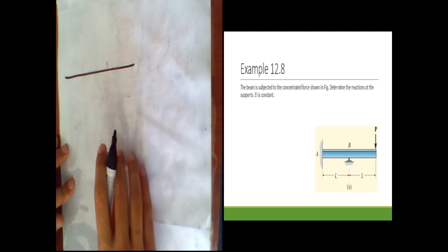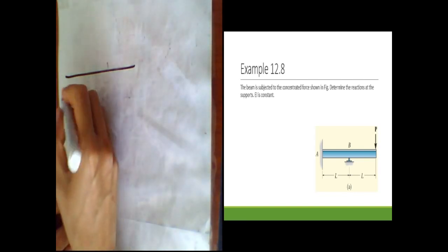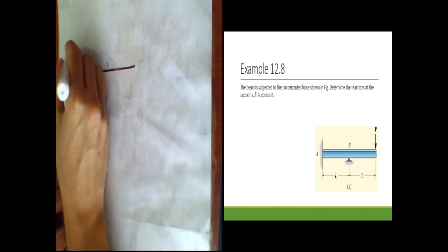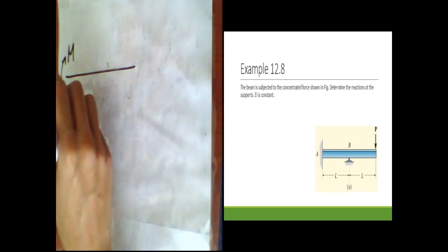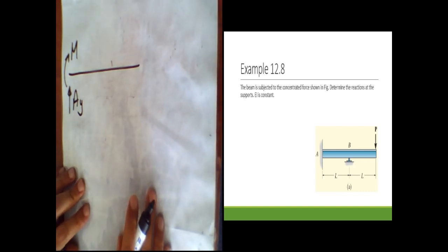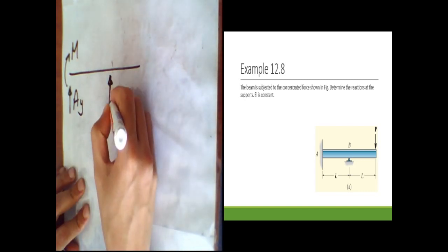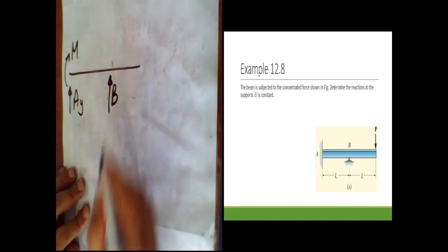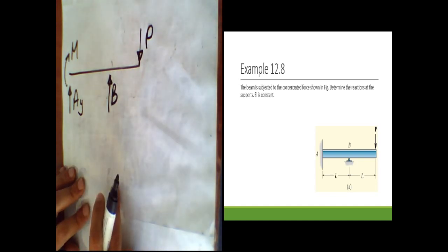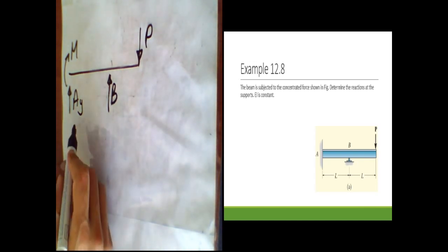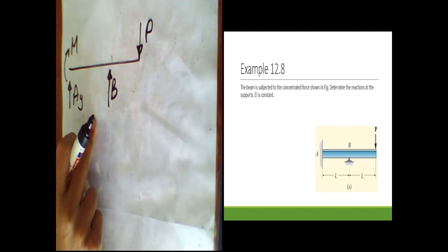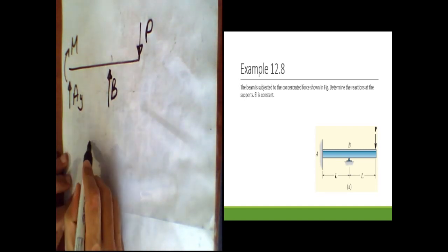Normally, if I want to draw the free body diagram, here I have Ay and a moment. Also, I eliminate the horizontal force because Ax is equal to 0, therefore I don't write it at A. This is By, at B. So we have 3 unknowns, but we can apply just 2 equations, therefore we cannot easily find them. This is the whole free body diagram, the whole system.